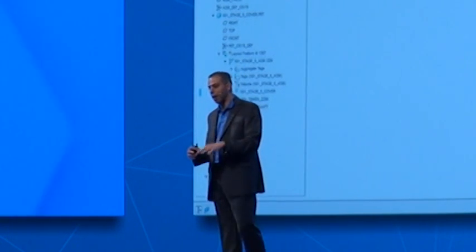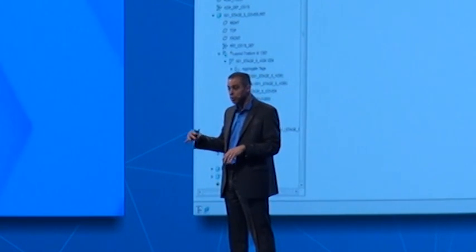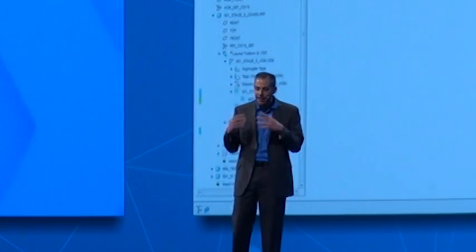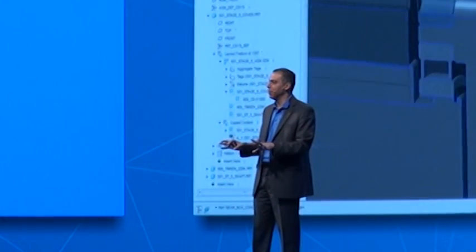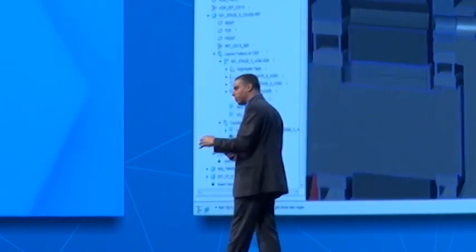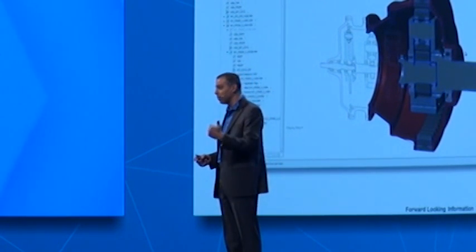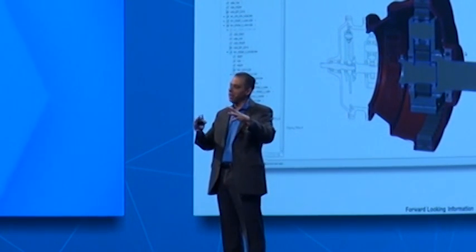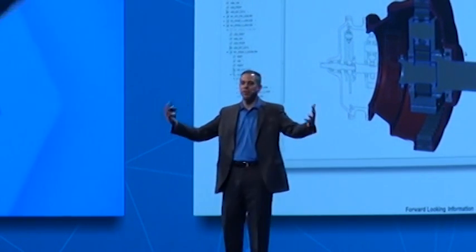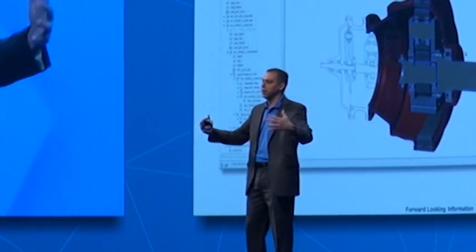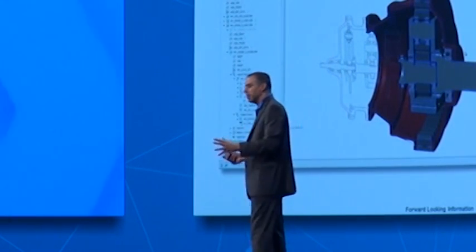You see it all there right in the layout, very nice and easy to follow. We actually have color coding of that in the model tree as well. So you can see all of that together at one time. And now, when the change is brought into Creo, when I hit that update tool, I know exactly what's going to happen, right? So I'm well educated about exactly what's going to happen before I accept that change from 2D to 3D. Okay, so Creo Layout, a lot more scalable. With the introduction of sub-layouts, you can take your design, break it down into pieces, and work with much larger layouts. And with this greater scalability comes the added benefit of a much better 3D integration that gives you a view of exactly what's changed and how it's changed before you accept changes, okay?